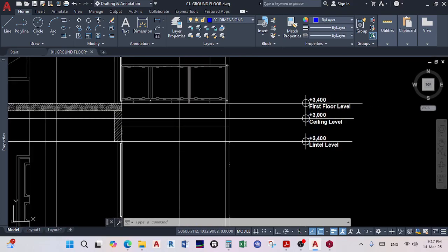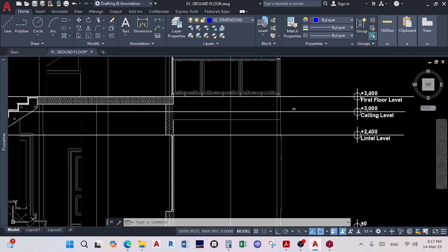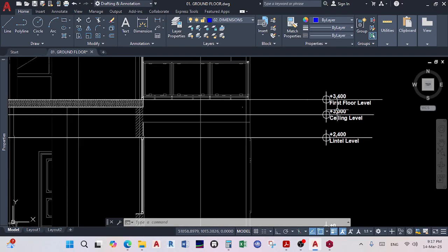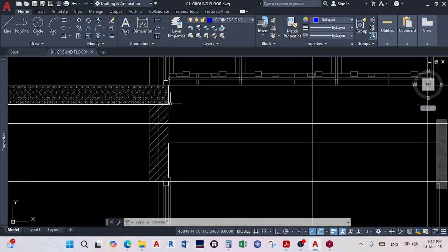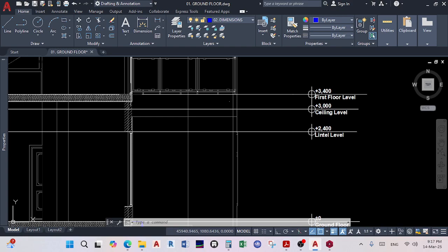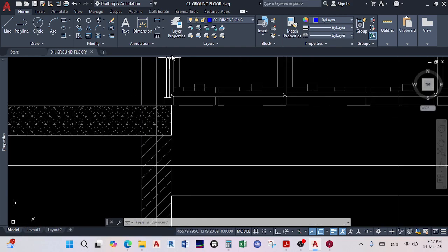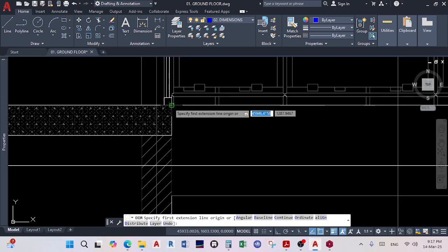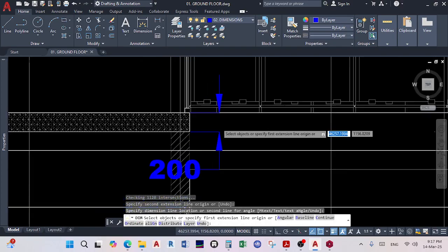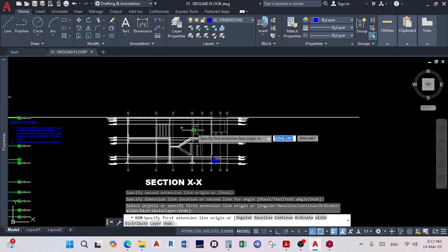Because remember what I said in one of the videos, usually structural engineers, their elements, the top is like 0 and then it goes down. So here I like that the architect got it right for me personally as a structural engineer. He shows that it's not counting from the bottom of the slab, it's counting from the top of the slab as 3.4. So there I can just go in, and I'm pretty sure maybe he used like a 200. He wants to use a 200 slab, okay, good.